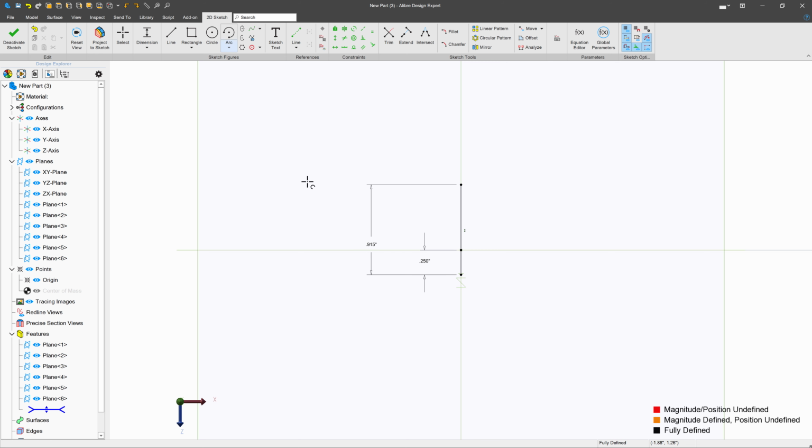Next, I'll do an arc right there. And we'll make sure that this arc center is vertical with its endpoint, which as you can tell it is, because we've already got that constraint on there, which should be that little perpendicular constraint. So because the end of this arc is perpendicular with this line, we know that this arc center will never vary from being vertical with the origin.